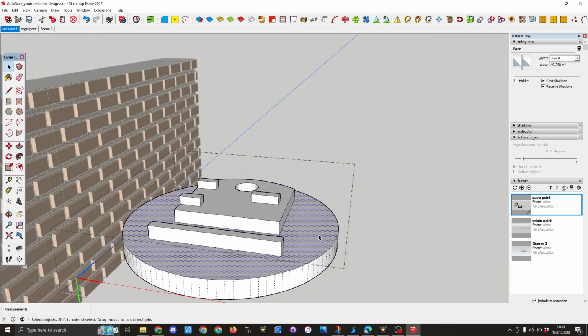So here you can see once I can start highlighting parts, I'm in the component, and I want the offset tool. I'm going to pull it in 0.6. Press enter. I'm going to select it again. I'm going to reduce the number of segments to 20.